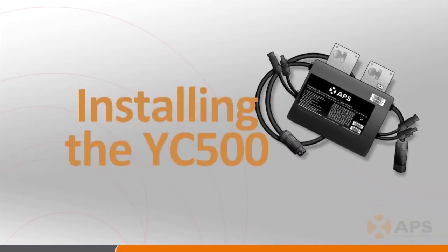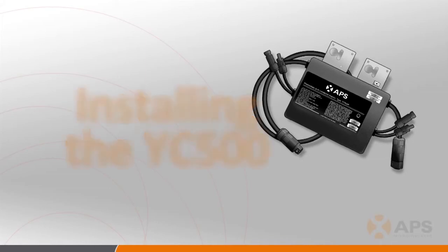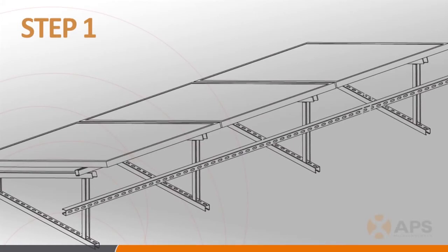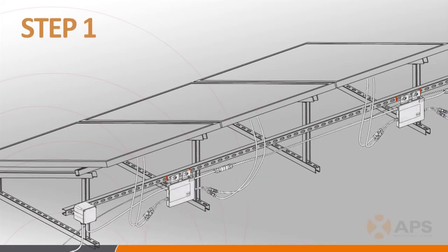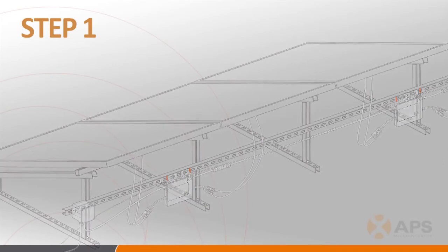Okay, with all the background information out of the way, it's time to start walking through the actual installation procedures. Step 1. With the racking system installed, lay out and mark on the racking where the YC500s are going to be installed, keeping in mind where the PV module junction boxes are going to be located and avoiding any other possible obstructions. Then go back and install the inverters using your marking as a guide.